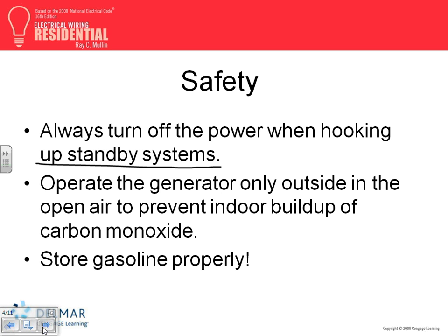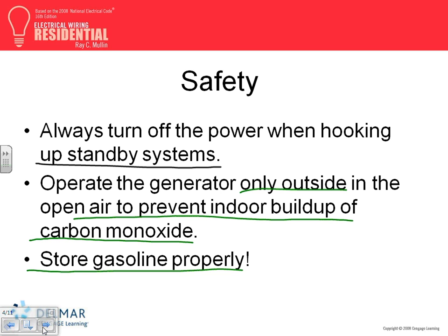Operate the generator only outside. As you guys know, generators burn natural gas or diesel or some type of fuel, and of course you don't want to burn this inside your house and have carbon monoxide and hurt yourself. Store gasoline in properly located places. You're talking about turning the power off at the service coming off the main before you hook up your generator.